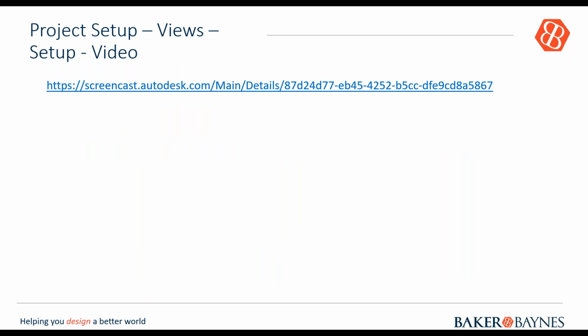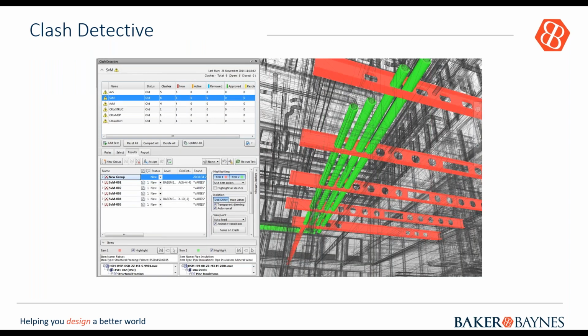So the first step, just a quick recap before I go into any clashes. First thing that you do is you need to plan, right? And the process for setting up a coordination model, the first step is to append the file, upload the files, make sure the files have the correct coordinates, right? Once that is done, you then go into your drawing and you create viewpoints.